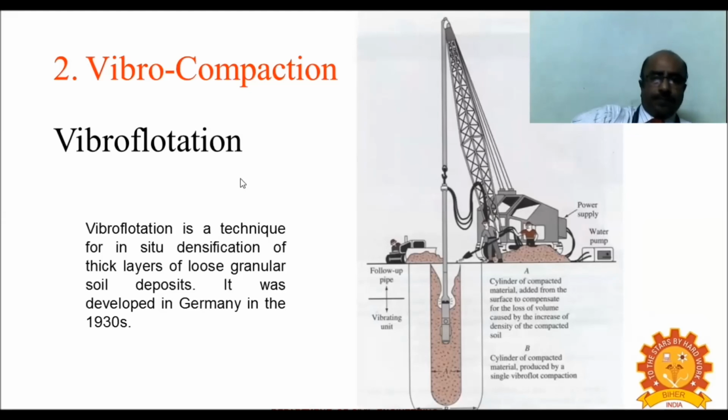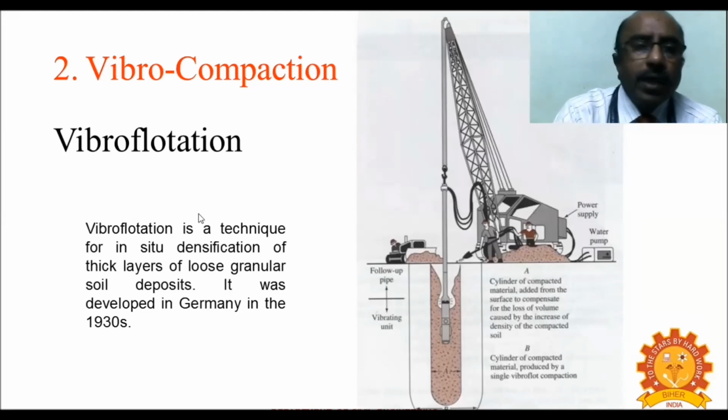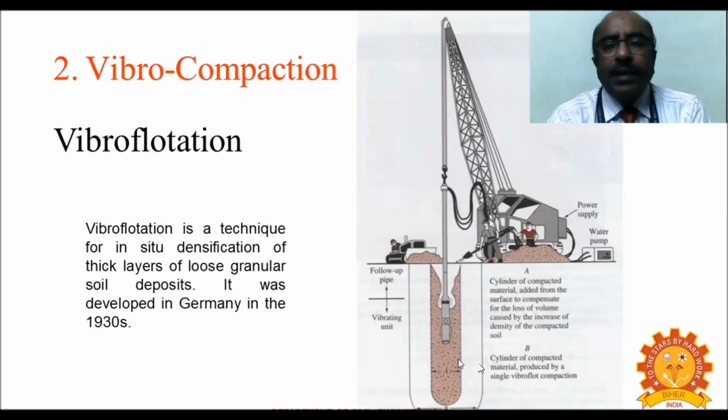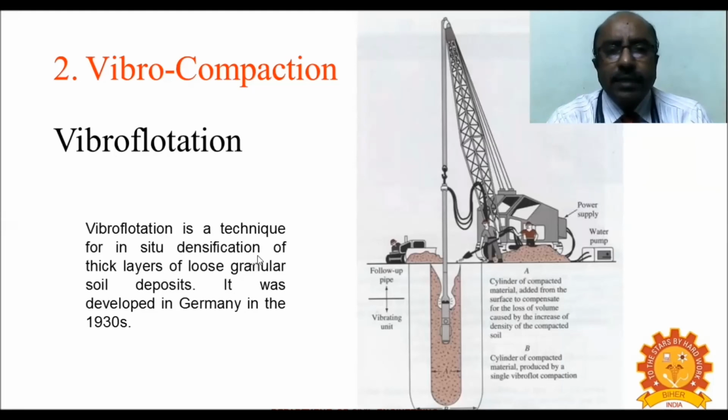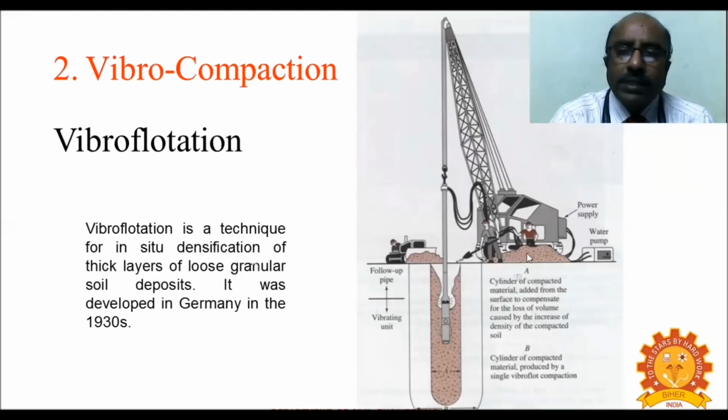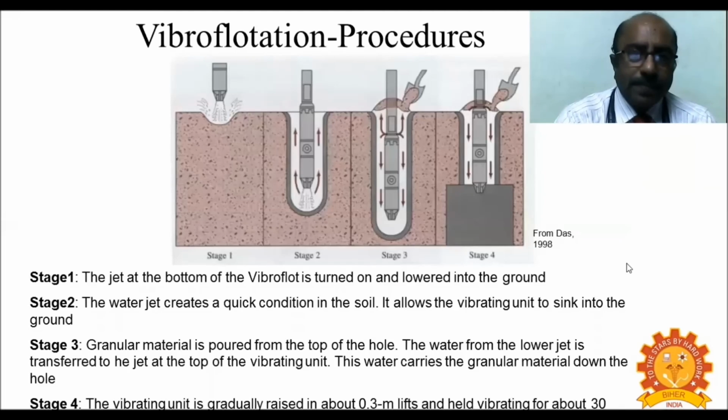And next is vibro-compaction. We can go for vibrating the soil and then fill it with some other material. That is called vibro-flotation. These are techniques for in situ densification of thicker layers of loose granular soil deposits. This technique is very sophisticated, but very fast.